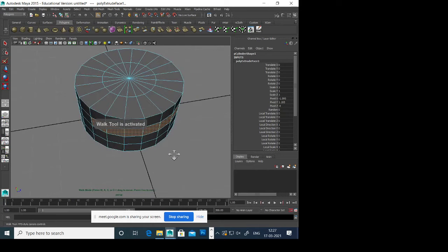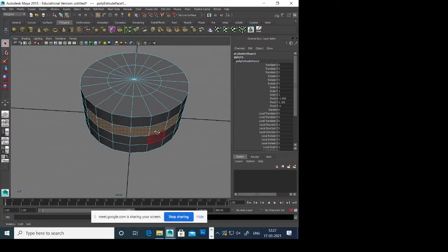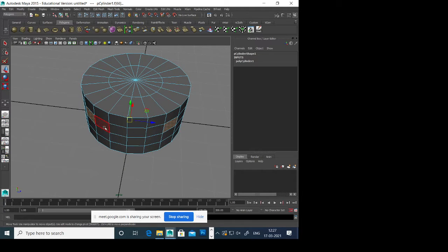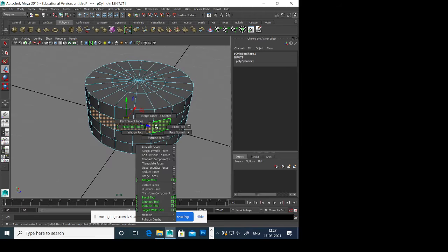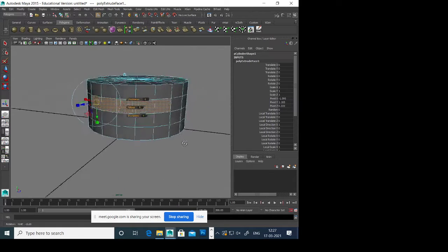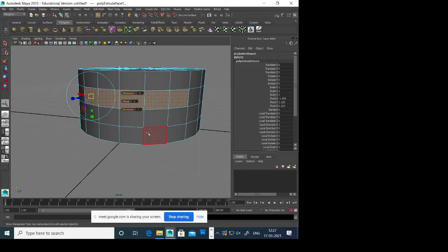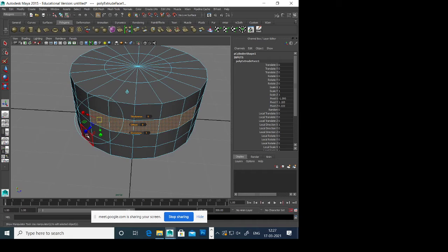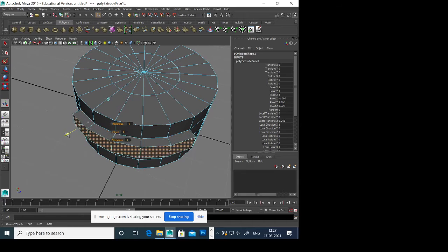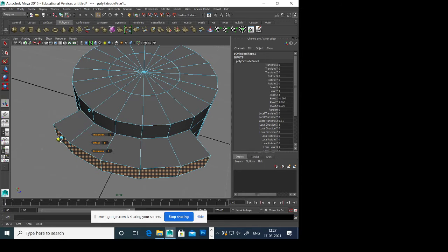Select this, shift, extrude, and now you can see you have the options thickness, offset, division, and you have this angle. You can see there's a scaling option plus a move tool, both combined. So if I click move, I can move the model, then I can scale. Suppose this blue one, the X Z direction, it won't scale, but red, if I click, it will scale.